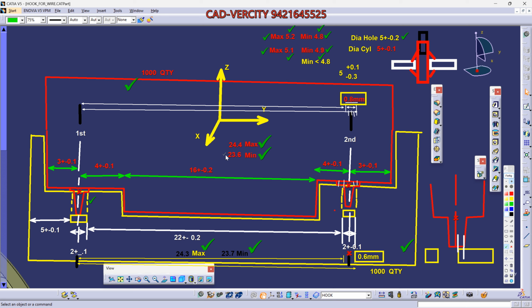So Pranali, whatever we are doing, the plus minus of all tolerance in one direction, the plus minus of the second part tolerance in the same direction, we call it stack up. We are summing up all tolerance with the total dimension. Then we will calculate whether your part is okay for assembly or not. Got it? Yes, sir. Raja, Nitesh, everyone. Yes, sir.